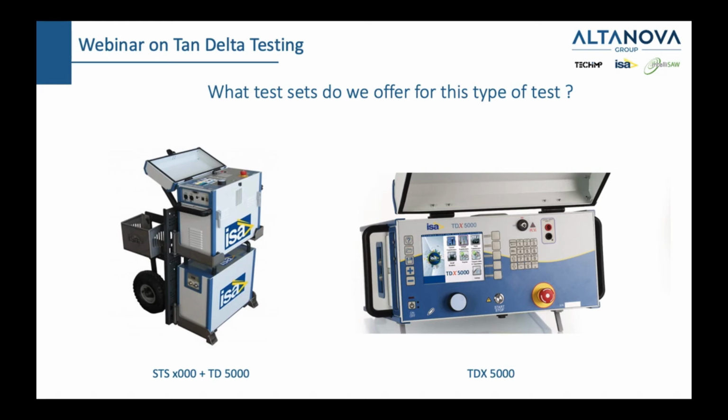And why is it considered tan delta value more than 1% for a distribution transformer? That means resistive current is more to produce heat dissipation. Well, as I said, these numbers are not written in stone for a transformer, a distribution transformer which has a lower voltage, let's say lower than 60 kilovolt or even lower than 11 kilovolt.